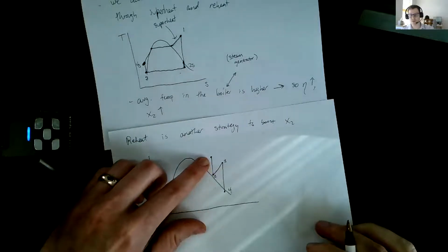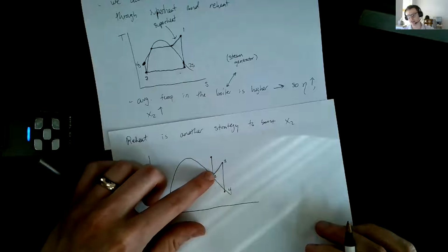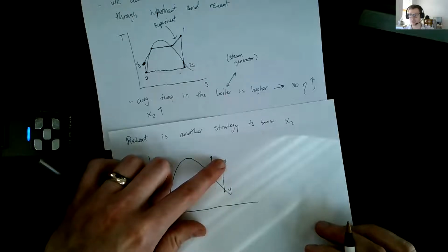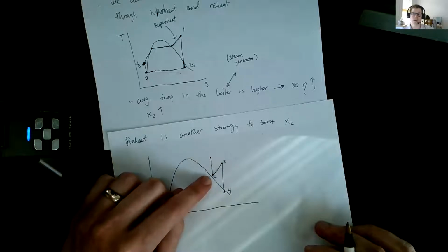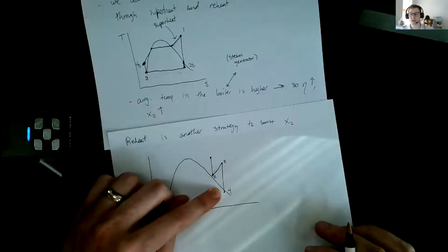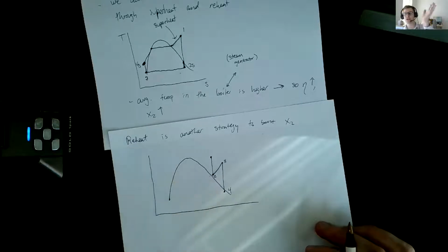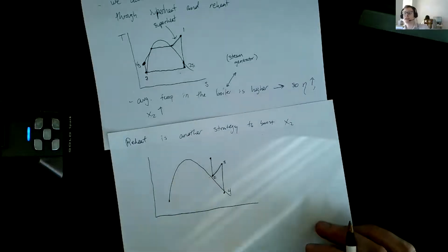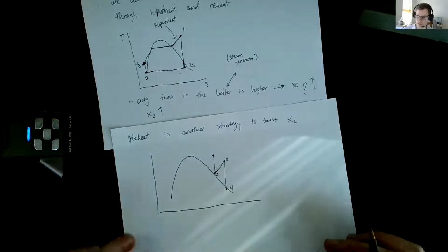So you can see we're basically extracting the same amount of power in the end, right? Because we have to pay for it by putting in more heat. So it's not like we're getting more power out, but we're avoiding the issue of running a two-phase mixture through a turbine. We're basically trying to keep the quality on the right side of the saturation curve. We're trying to keep those turbine states on the right. That's what we're doing with reheat.